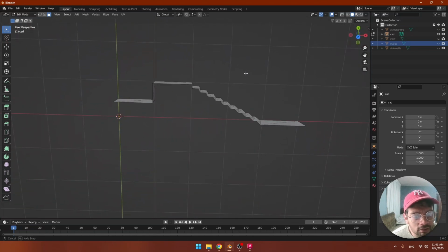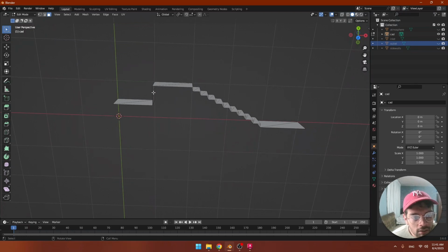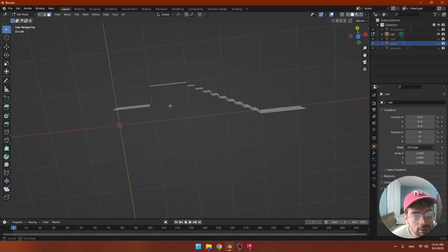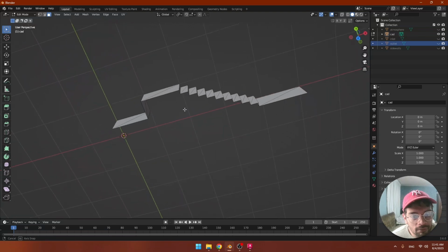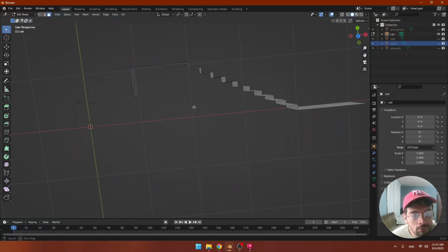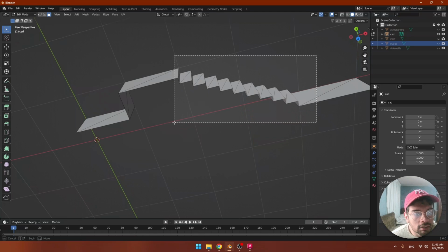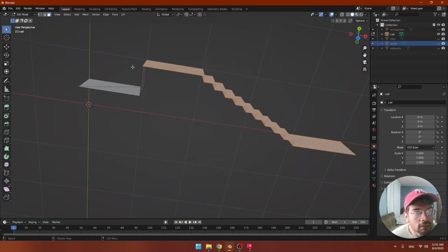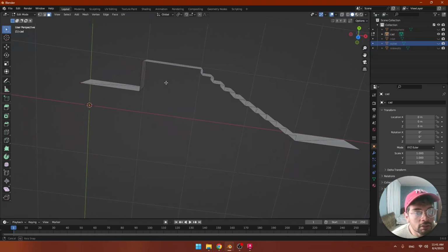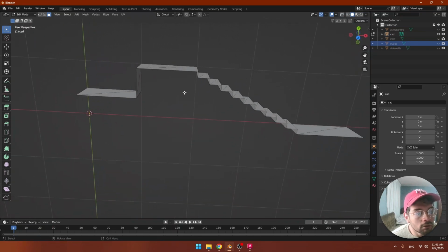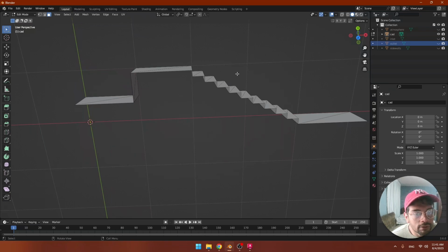always like to make this differentiation in the bottom layer, because the flow is going to be more complex in this case, in these phases, than in this one, basically because of velocity. So we're going to need to have the finer mesh in this area. So we're going to first select these ones, and we're going to call selection.